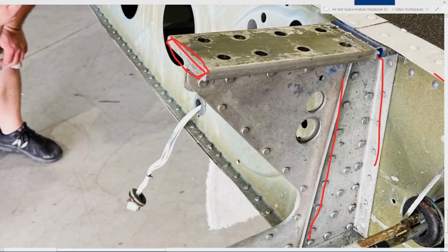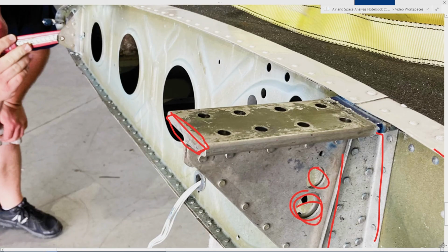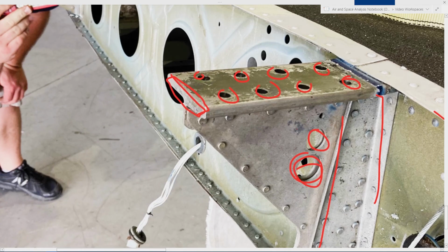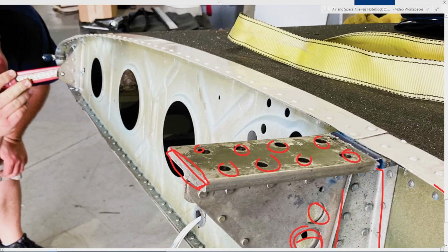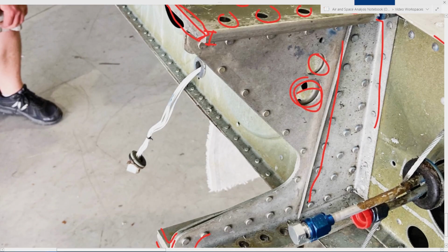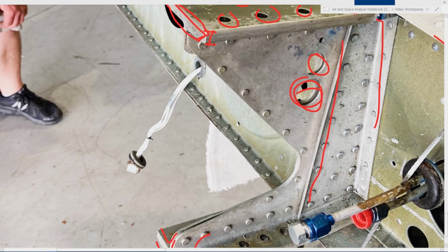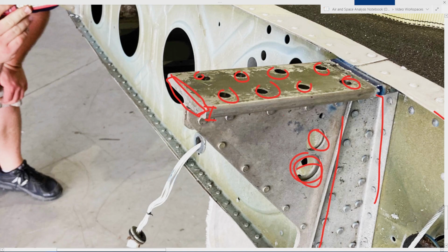It's connected straight through to the rib. We have these big bolt holes that mount the structure. We have these big ones on top, which will mount the wing root. So the moral of the story of this picture is that we have a ton of material. We're still modeling 0.091, where this is more like 3/8 or half an inch, like 3 or 4 times what we have, and it's a fairly integrated structure into the geometry of the spar here.